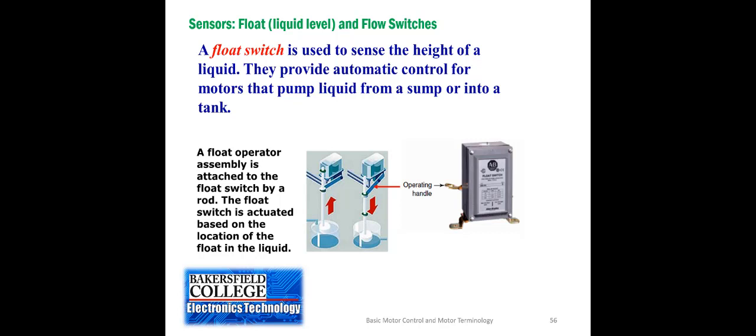Now, if there's liquid flowing in there consistently, then the pump will operate almost continuously, and that's okay. But when there's just a little bit of liquid, we don't want the pump turning on and off constantly. We want to use it efficiently.